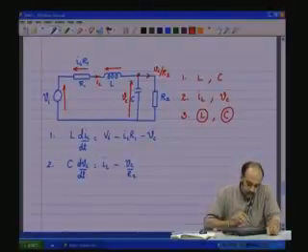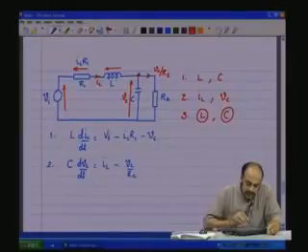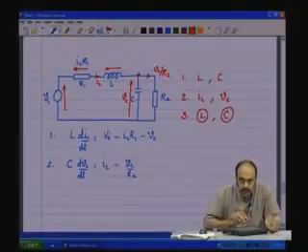So, therefore, try to identify that state variable which will decide the voltage in this one. And as R is in series with L, the state variable IL is used for finding the voltage across R. So, IL R1 is the voltage across that one. So, all the elements, the voltages across them have been identified.